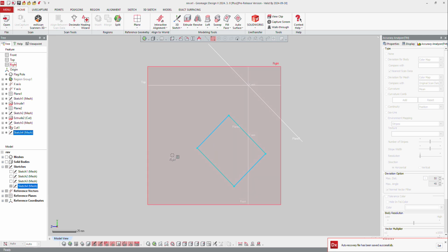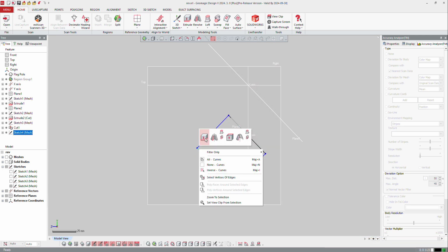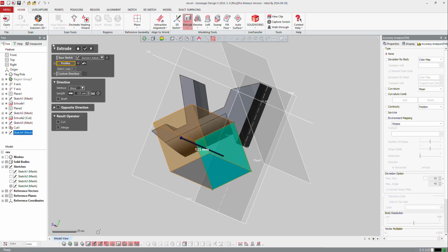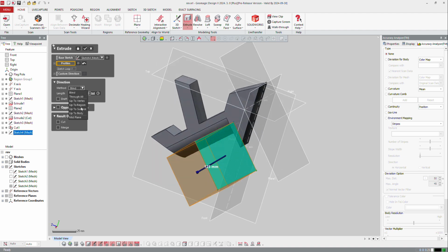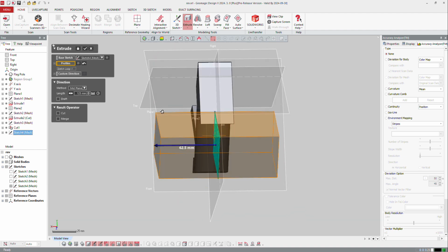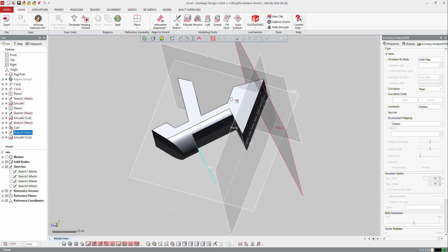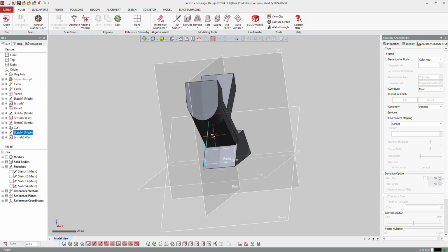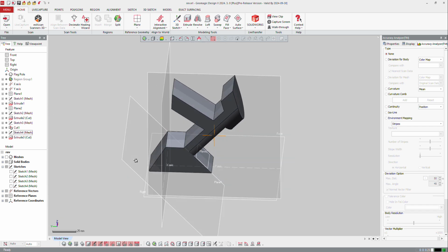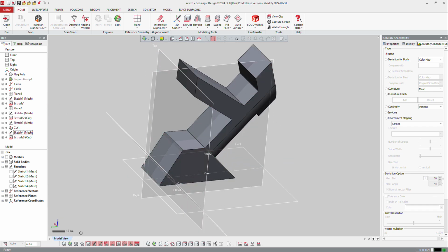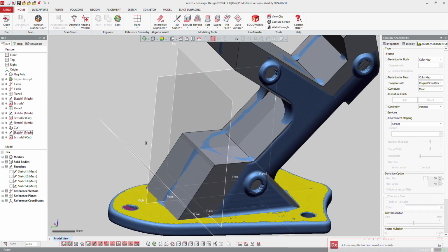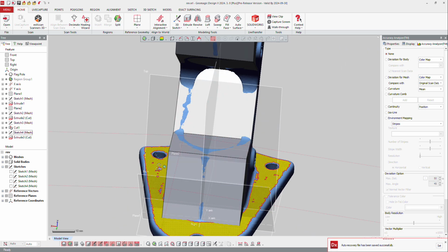From that, I will just extrude, display my solid body and extrude it mid-plane just to cut the model. So I do not need to make it too big, so maybe 60 millimeters should be enough, and cut. And okay, so now you get a nice opening here, and I can continue the part by just making maybe this area. So this area, if I look there, it's a fillet that goes from here, touching this area and ending over there.